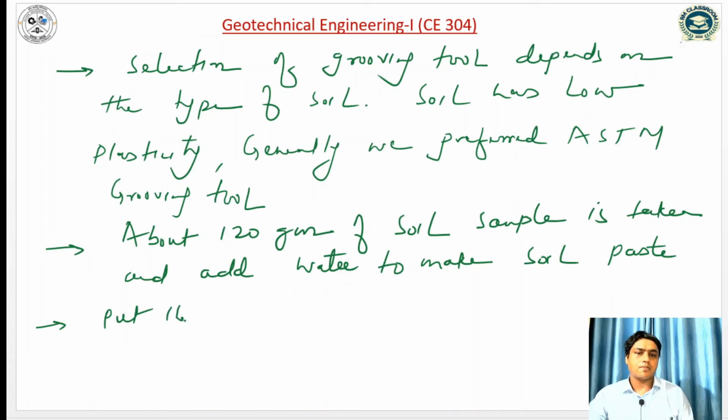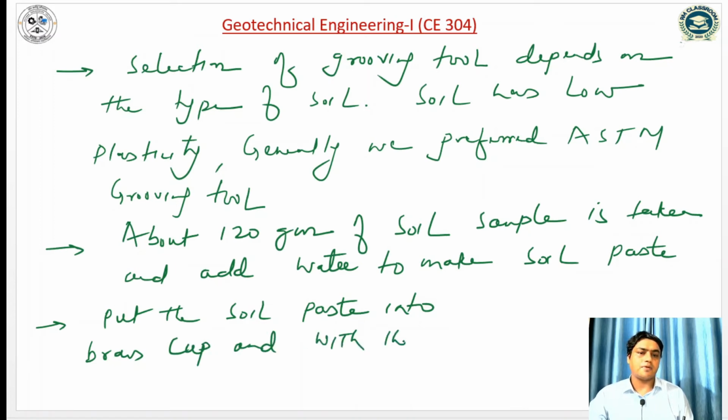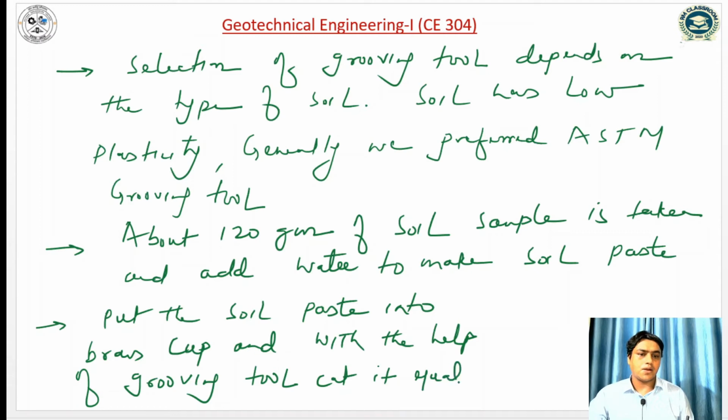Put the soil paste into the brass cup, and with the help of the grooving tool, cut it into equal parts.